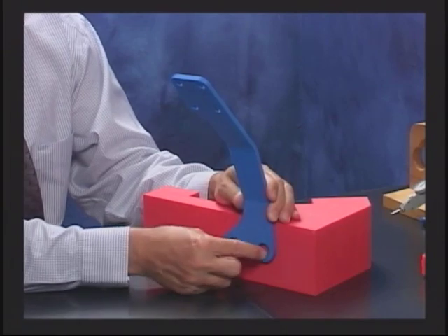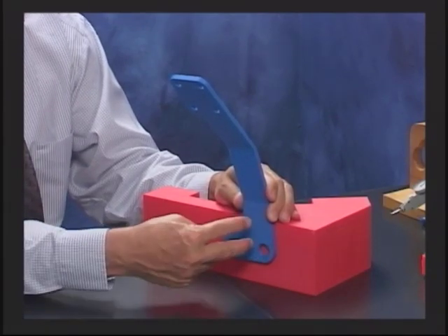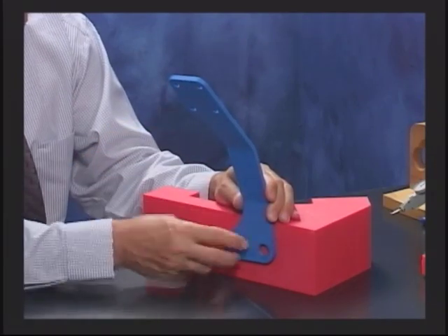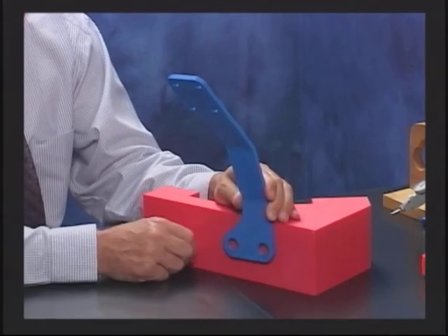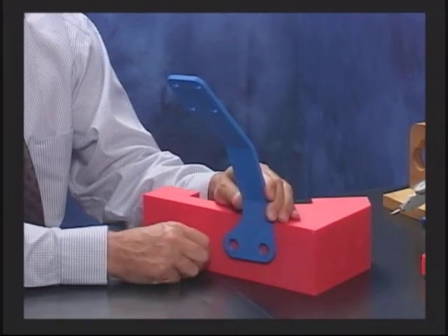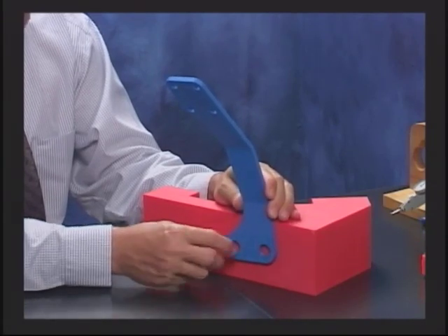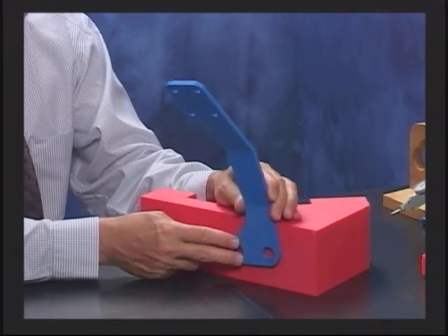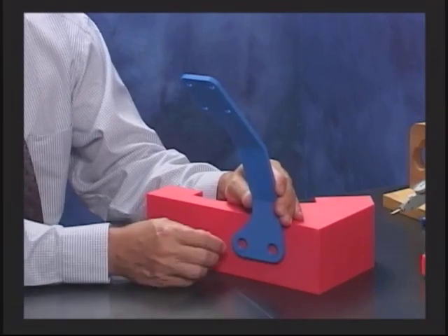The distance between those 2 holes is very short, doesn't it? See that distance is very short? If I take a look at it at a ratio here, 1, 2, 3, 4 times as much. So if these holes were spread further apart, it would locate this part better. But since they're so close together, it's really not going to be able to locate this very well. So MMC allows these holes to move around. I put it on the bracket, I can adjust the bracket, fixture it where I want it, and then bolt it up.